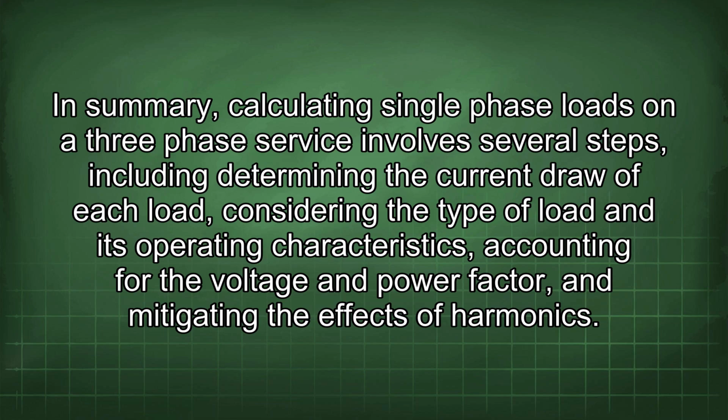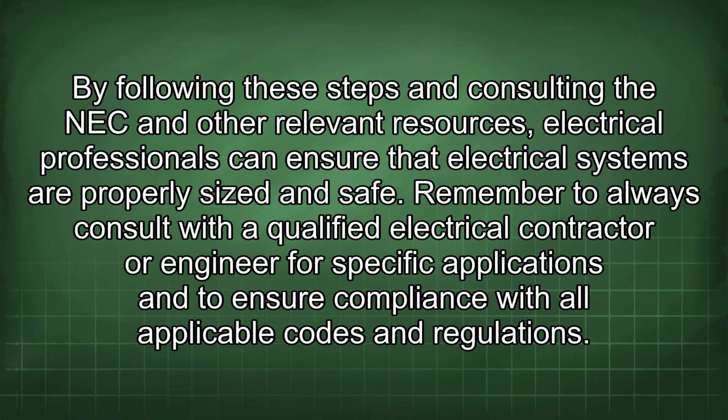In summary, calculating single-phase loads on a three-phase service involves several steps, including determining the current draw of each load, considering the type of load and its operating characteristics, accounting for the voltage and power factor, and mitigating the effects of harmonics. By following these steps and consulting the NEC and other relevant resources, electrical professionals can ensure that electrical systems are properly sized and safe.